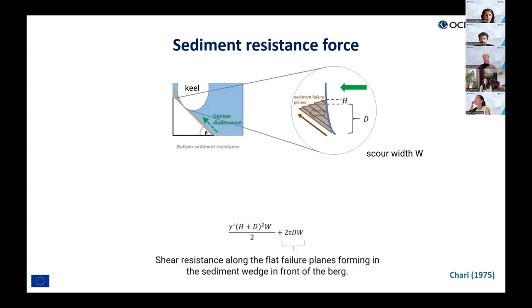In addition, within this sediment wedge in front of the keel, we form failure planes, and as they try to slide along each other, there's shear resistance that prevents this wedge from sliding forward.